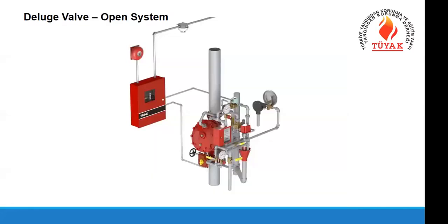And we have another system called the deluge valves. The deluge valve systems are used mainly in spray systems that have open sprinklers or open nozzles. That means they don't have any temperature activation devices. All are open, and when you send the water from the main valve, all the nozzles or openings release water at the same time.